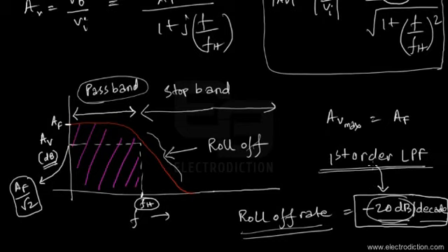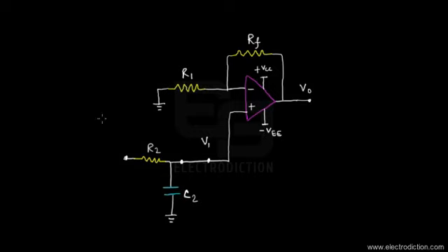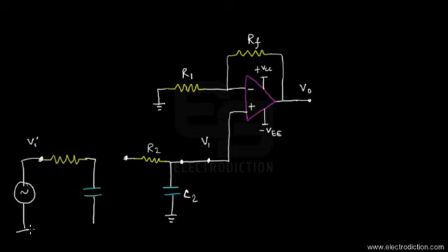Alright, so that is also one of the reasons why we call this circuit a first order active low pass filter. Now if we use the same first order active low pass filter circuit with another resistor capacitor stage at the input, so if I'm drawing it somewhat this way, if we have one more capacitor over here, then we get another RC stage, and apply the input voltage from the sinusoidal source right over here, and then join these two together.